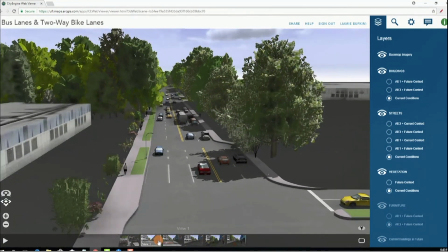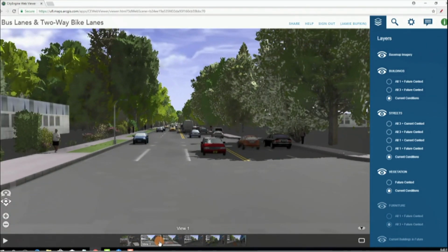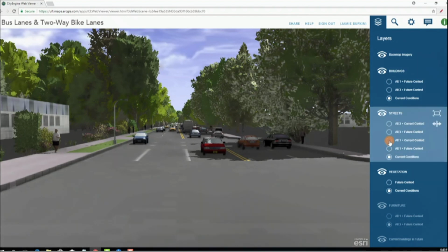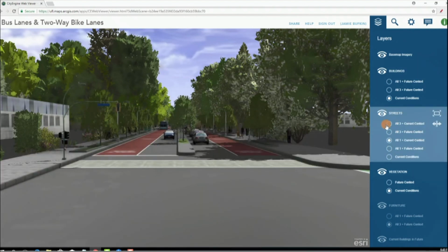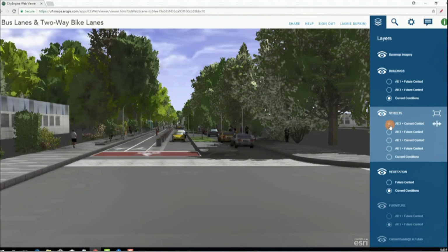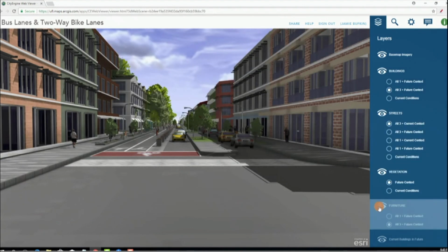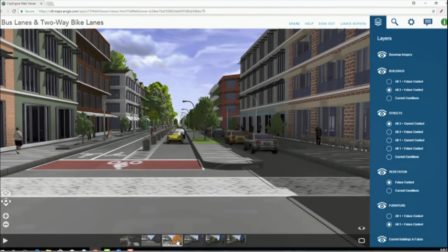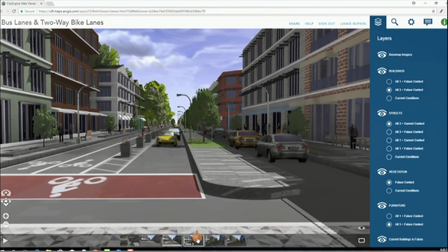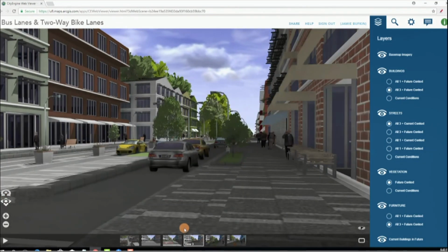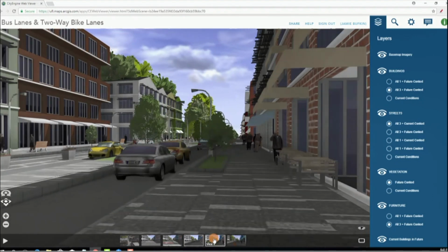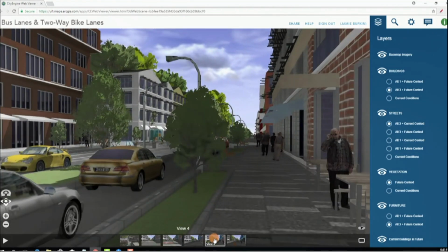What this does that we like is you could have these spatial bookmarks of the views at the bottom. You can set a few of those, press the play button, and it flies through those bookmarks. So in a sense, it creates some crude animation if you want to explore the space that way, but it's pretty effective and very low cost. You could create movement by just inserting more bookmarks, and for those of you familiar with animation, these are like keyframes that you set up when you post the web scene.